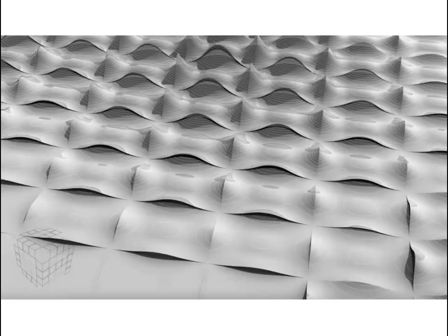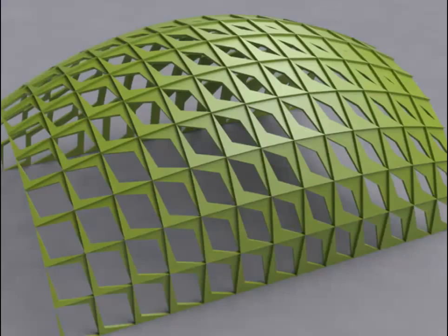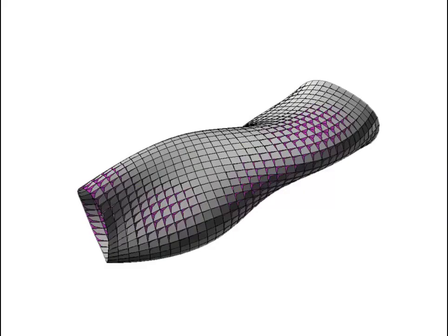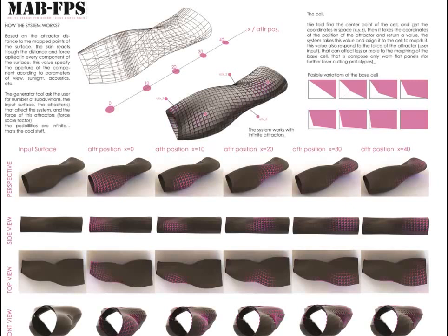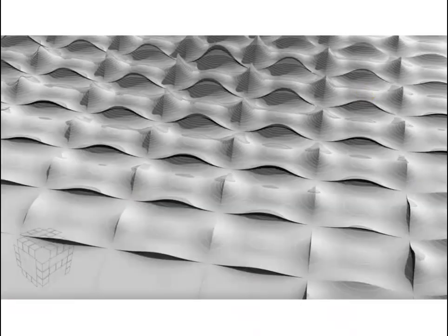So there are all different ways of basically taking an attractor, looking at the distance, and then with a little bit of math, equating that distance to the distance between these 2 points on a surface, or the choice of whether to choose one of these tiles or the other. There's probably a threshold. So let's say the distance is between 0 and 5, it's this tile. If it's between 5 and 10, it's this tile. You can set these up parametrically.